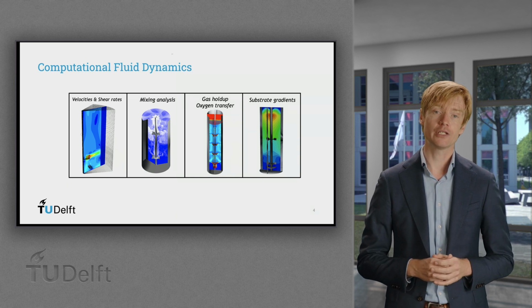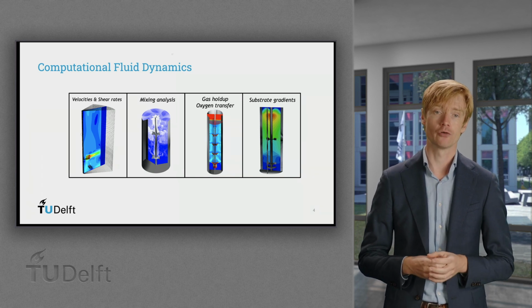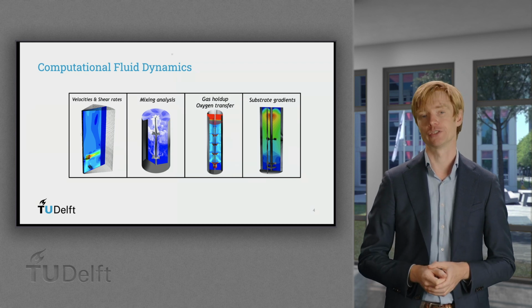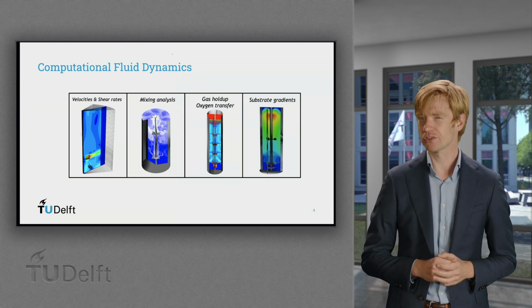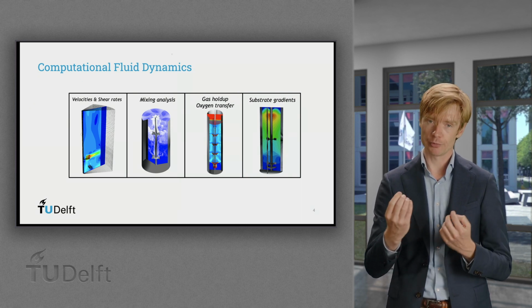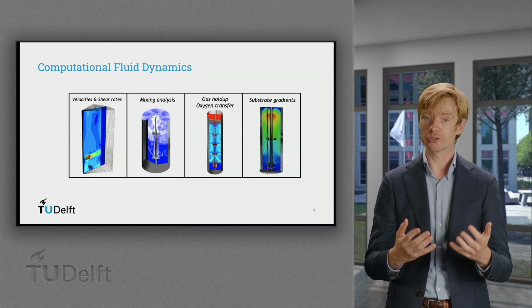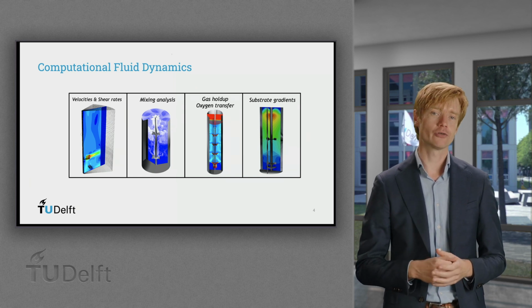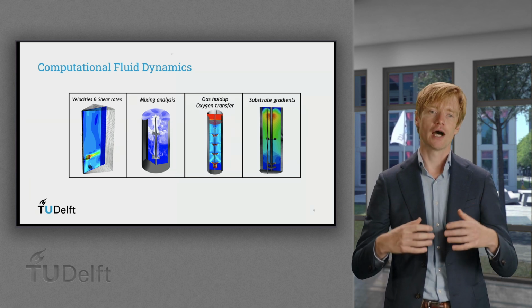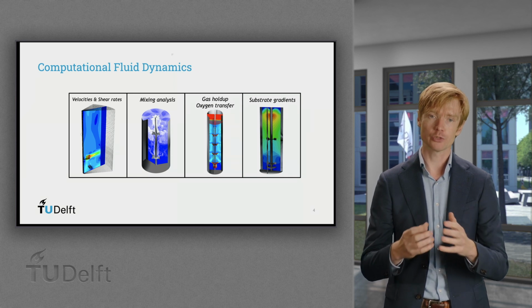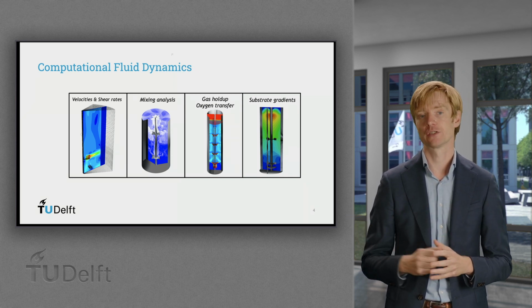Dividing a domain into many small grid cells to solve a set of equations is called a discrete or numerical solution procedure. For fluid flow, this is not straightforward. You need to solve several balances which are coupled to each other. But doing so allows you to compute local variations. An important factor in these balances is, of course, how things flow between these grid cells which we set up. In other words, we need to compute local velocities.